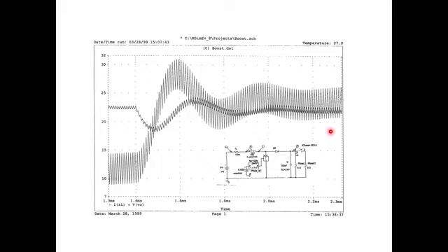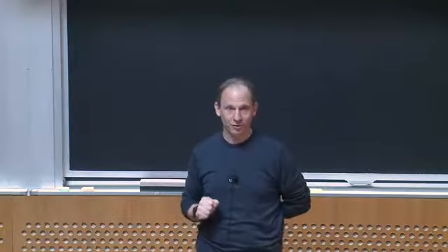Well, I'm not particularly interested in this switching ripple. Why am I not interested in it? Notice that the dynamical behavior is at a very low frequency compared to the switching ripple. And I can't really do anything about the switching ripple anyway. That's intrinsic to the converter: I'm going to put some energy in, process it through, and take it out. If I try to vary my duty ratio on the time scale of the switching, very, very fast, I'm probably going to make the converter do unhappy things.